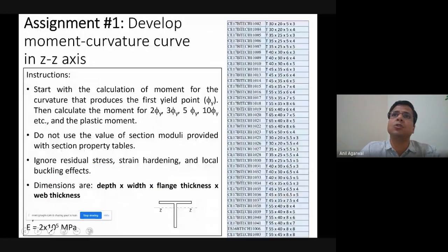If you go to IS 801, there is a limit state of local buckling as well. That means there are formulae given for designing a member against local buckling. However, in case of IS 800, you don't have to use any formulae to calculate the capacity against local buckling. You can prevent local buckling before yielding if you follow certain guidelines, and those guidelines are quite straightforward.